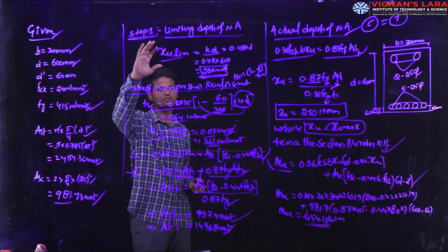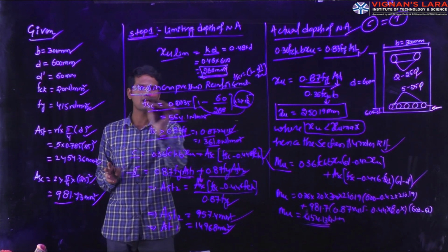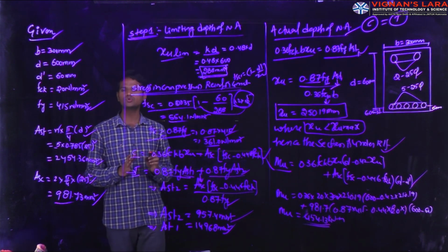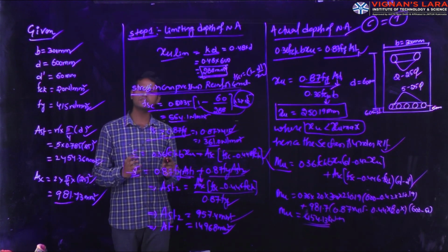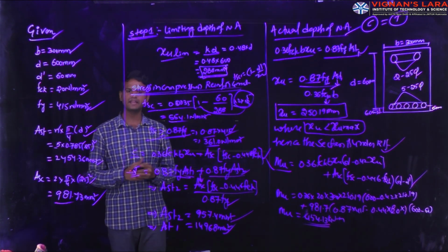Whereas for a doubly reinforced section, for calculating the actual depth of the neutral axis, always remember that the stress in the compression reinforcement is required. Why? Because to classify the area of the steel reinforcement in the additional section as well as for the limiting section.